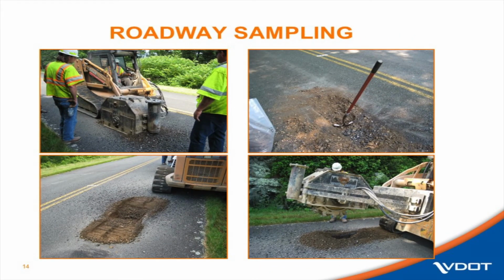I've done lots of roadway sampling, and I had my lessons learned. When I first started doing this, we'd go out there with a saw and chop out a block of asphalt and lug this thing back to the laboratory, and then figure out how we're going to break this thing up. So you put it in the oven, you start pulling it apart. It takes forever, it's inefficient. And at the end of the day, you're not replicating that blending action.